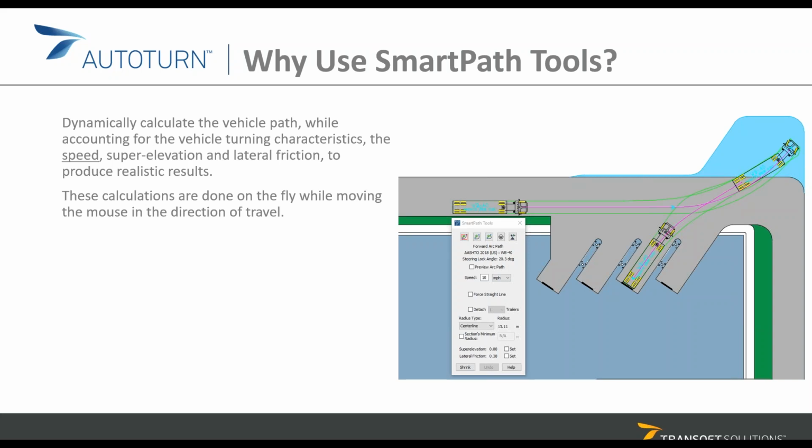One is the turning characteristics of the vehicle. The other one is the speed equation, as you know from AASHTO, which is essentially just the circular motion formula adjusted to have some comfort for drivers while on the road. And AutoTURN is constantly checking these two for the design vehicle and calculating which one is the largest to dictate the minimum turn radius for the simulation. That's all done in the background.